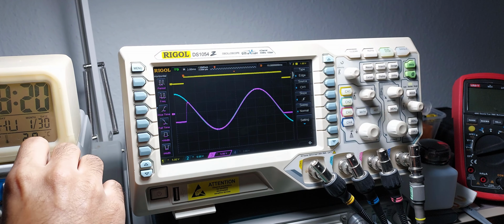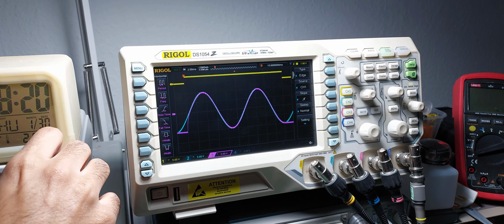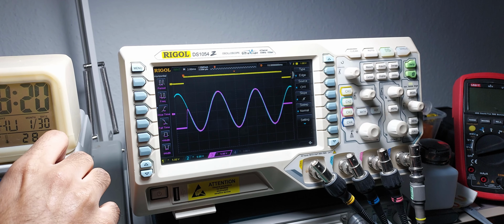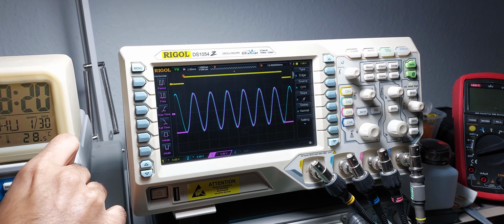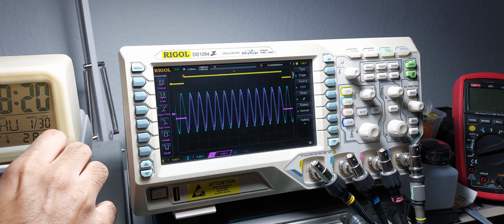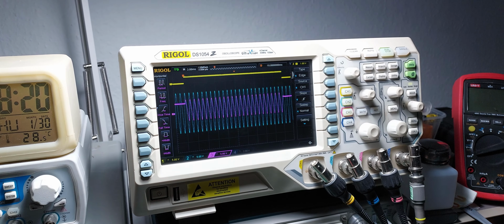The large sample capacitor, along with the on resistance of the analog switch, forms an RC low-pass filter, which limits the bandwidth of the circuit. This is not critical for this application, since the frequencies involved are very low, and my redesign does not call for sampling a changing signal.